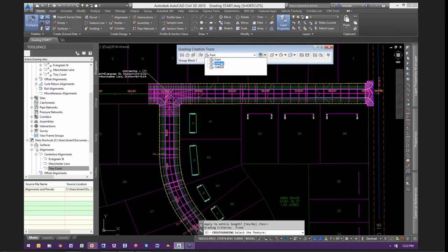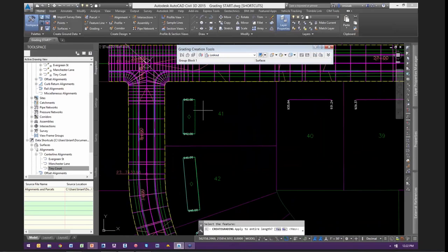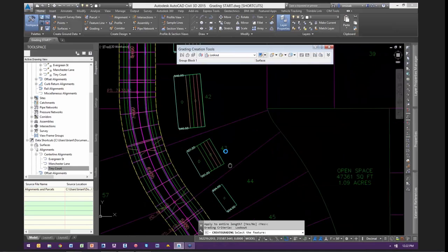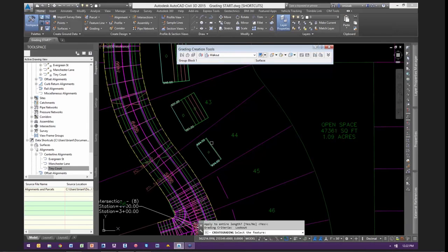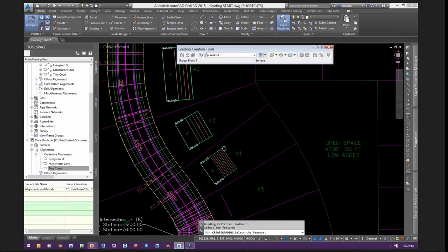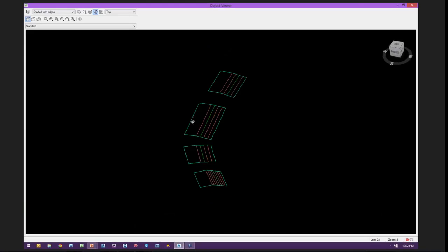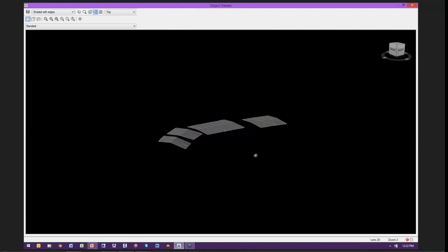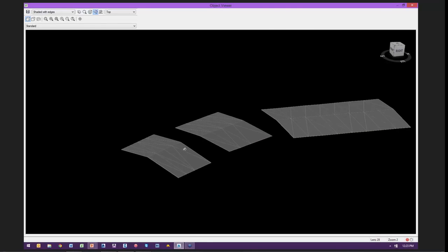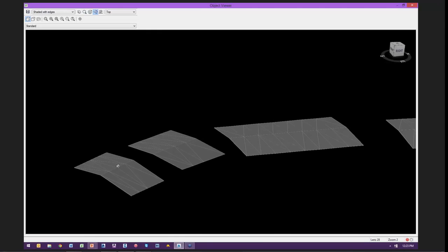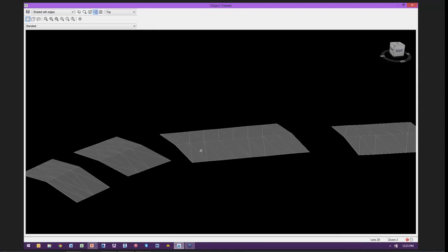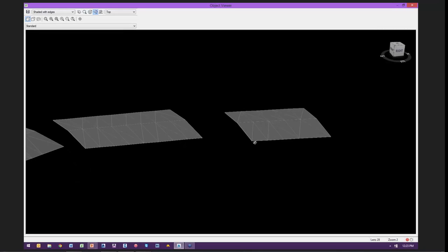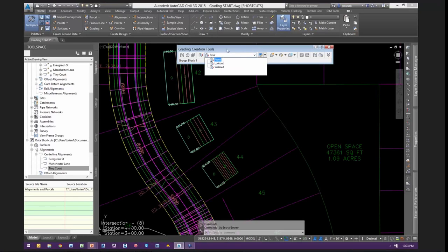Okay. And then let's say some of these are lookouts over here. And perhaps this one is a walkout. Okay. So what I'm creating so far, if I take a look at this in 3D, it's just the building pads. We'll worry about the areas to fill in between in a moment, but we're just looking at the building pad. So there's that flat top of the pad. There's a walkout, rough grading, and these are lookouts over here. Okay. A number of other options you would have as well. You might have some deep lots, any number of things. You can create grading criteria for that and put it right in a grading criteria set.